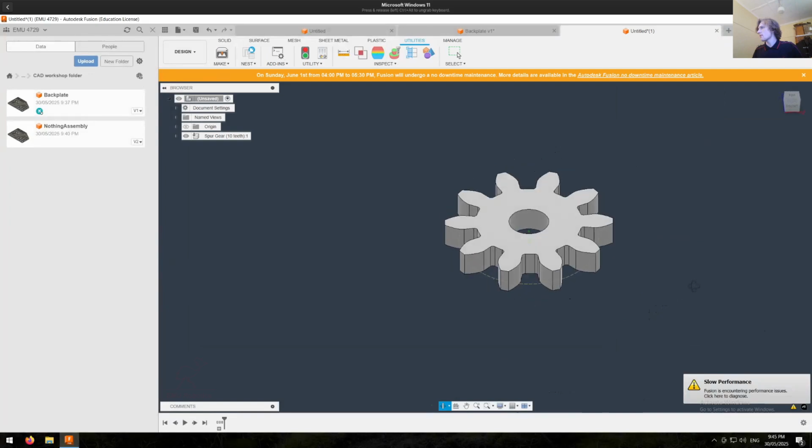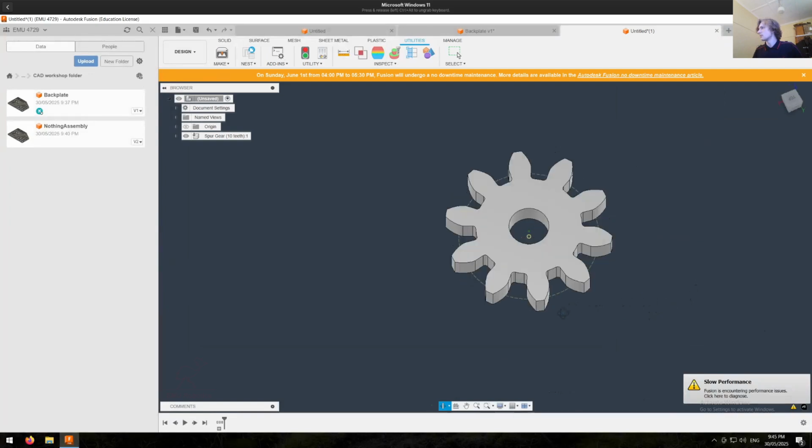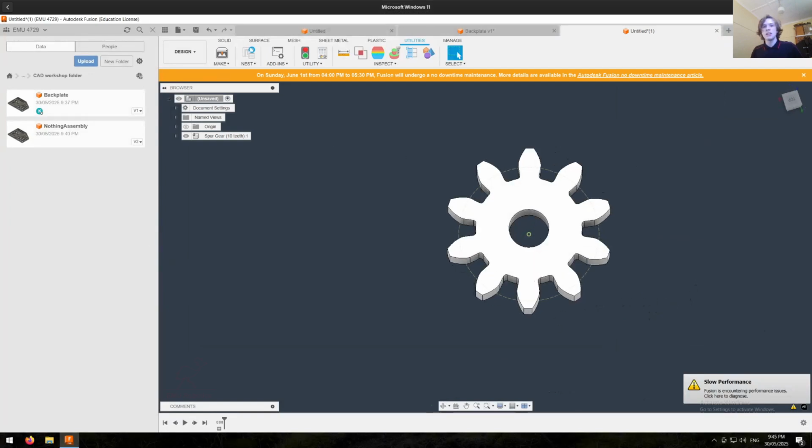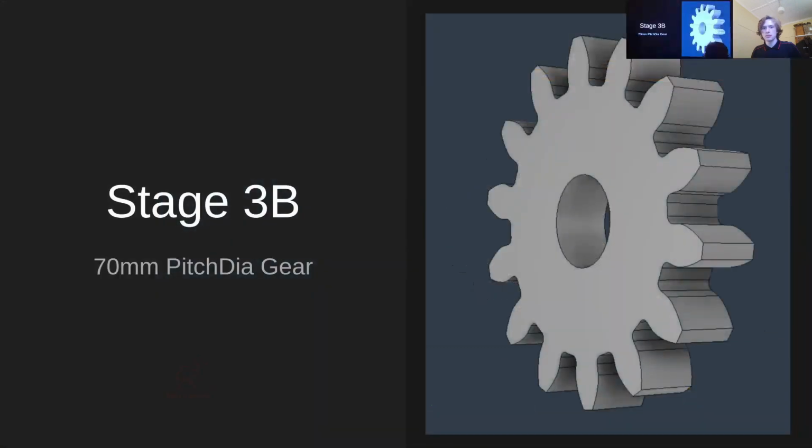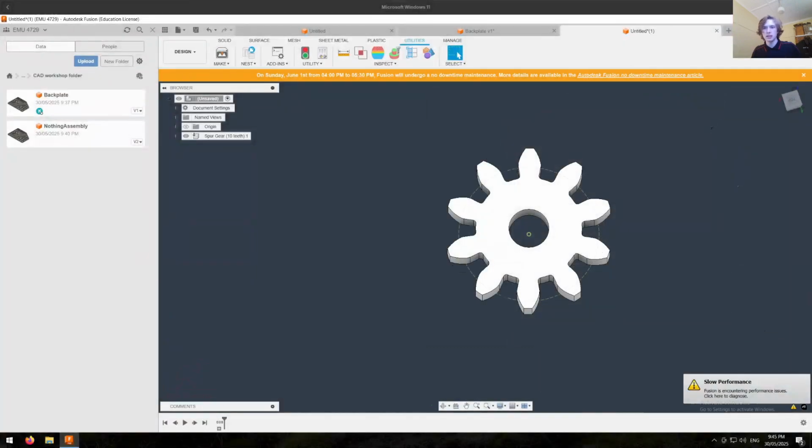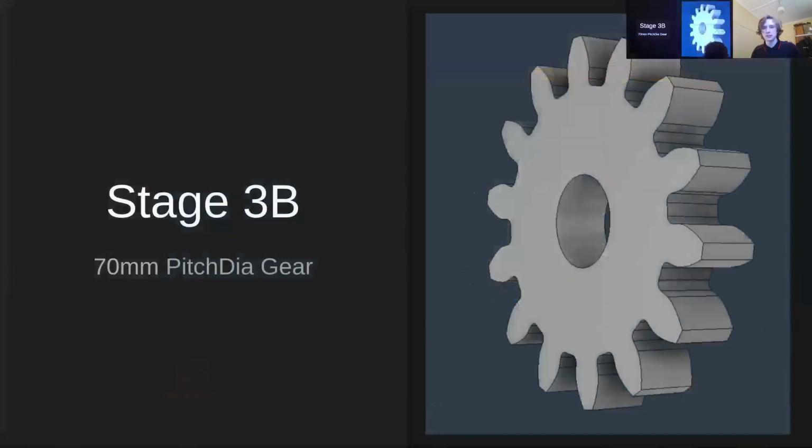And there we go. What a funny looking gear. But that does look different to the one that we want. Now, why would that be? Well, it's a pretty dumb question because we have 10 teeth on here and 14 teeth on this one. So no surprises there that it looks different. The real main thing that matters if you want 2 gears to mesh is that they need the same module. Other than that, you can just change the center distances and it'll work. As long as the module's the same, it'll work.